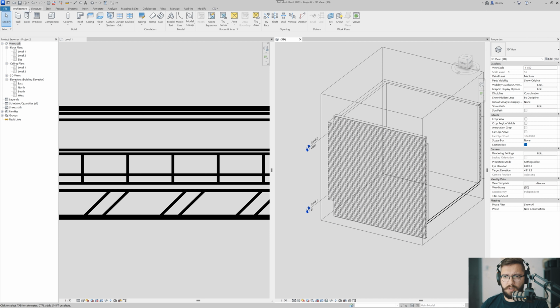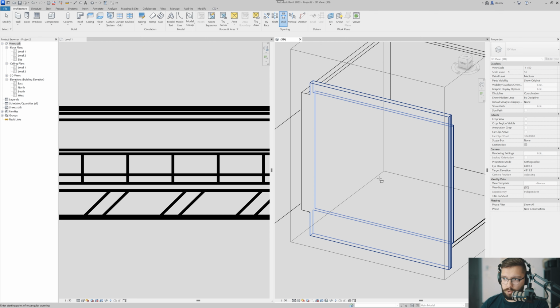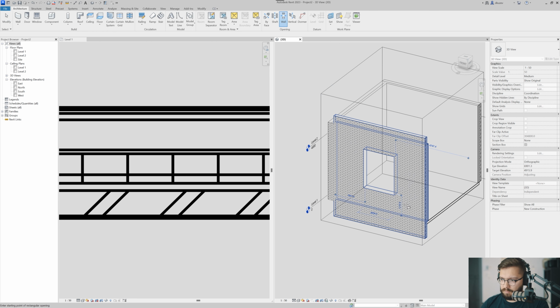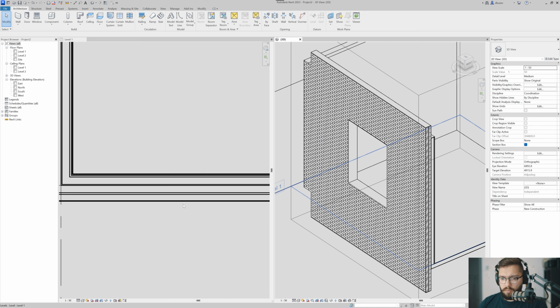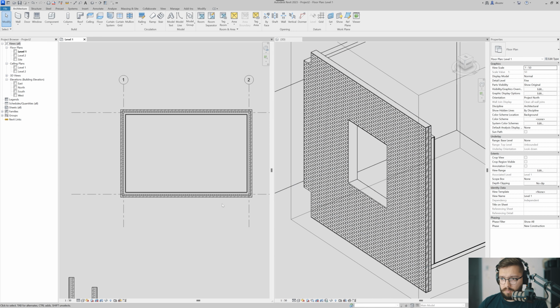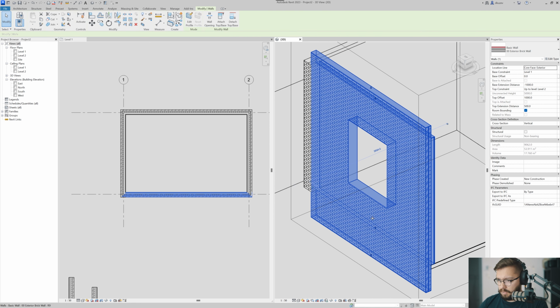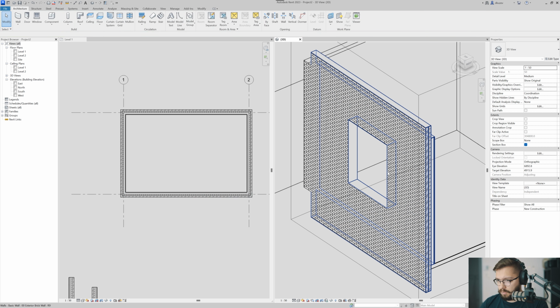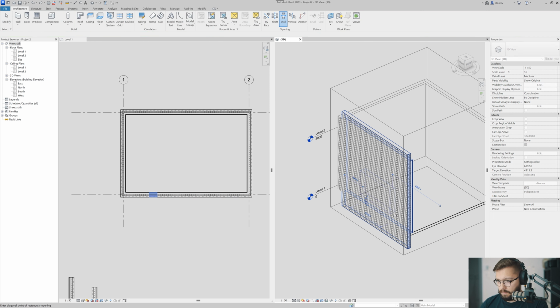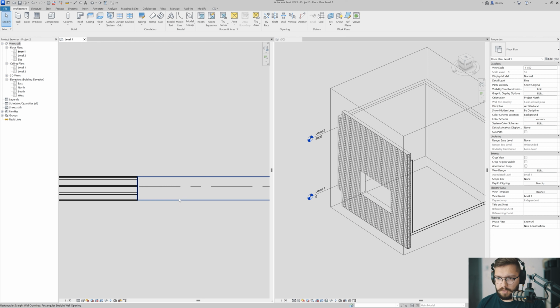And you can create a wall opening if you go to architecture, and then here to the right, there's openings, wall. Select the wall where you want to create that opening, and I just create a super random outline. So one of the things that you can see right away, all right, fantastic. So you see that I have this opening.